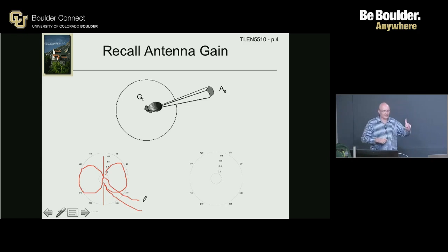So if it's a vertical dipole, its beam width in the azimuth plane is of course in all directions, same gain, which is why there's that circle here. That's the azimuth. And in elevation, its main beam is at elevation angle 0, but it doesn't transmit anything at elevation angle 90 degrees.